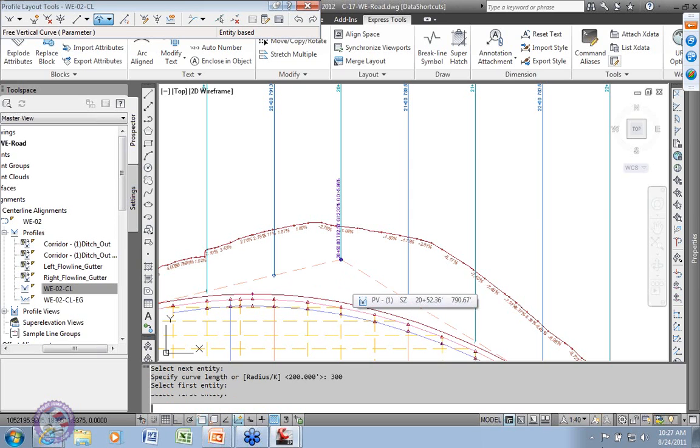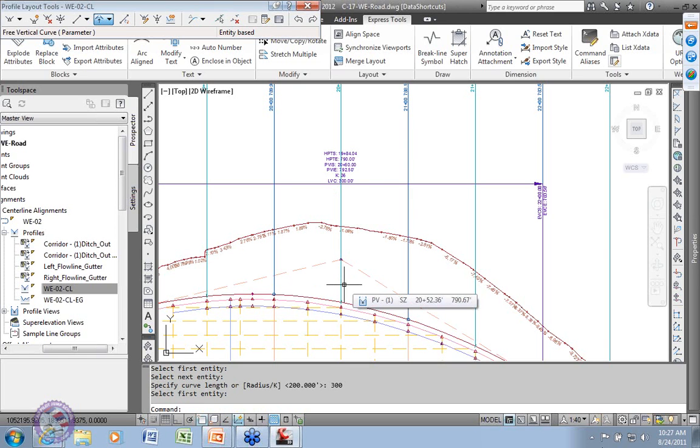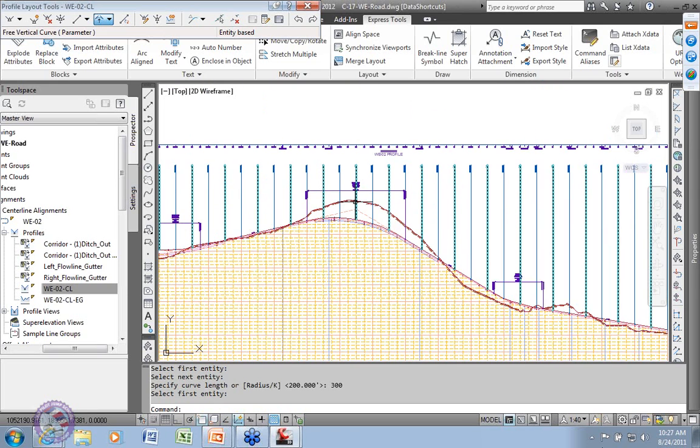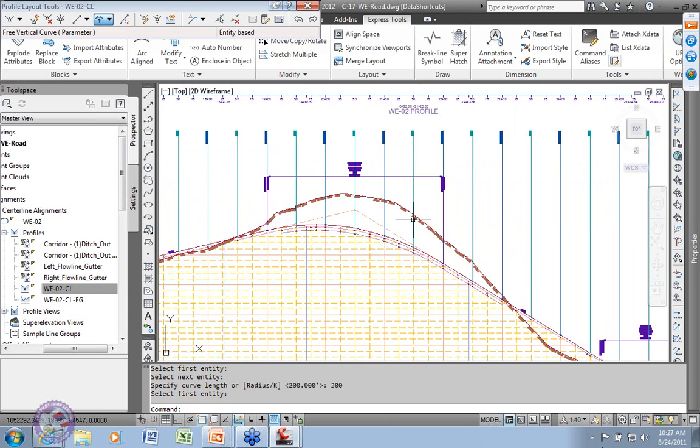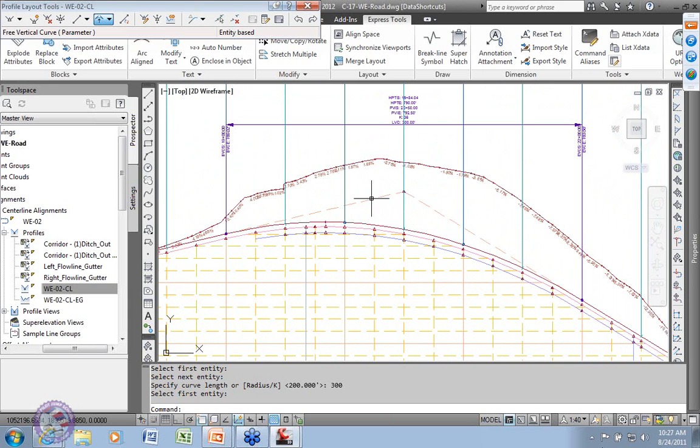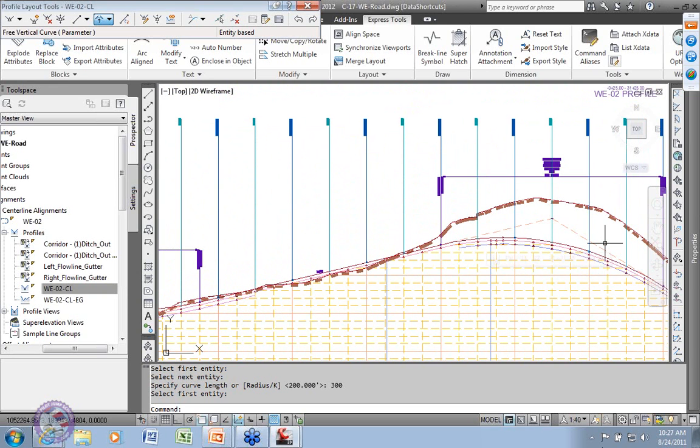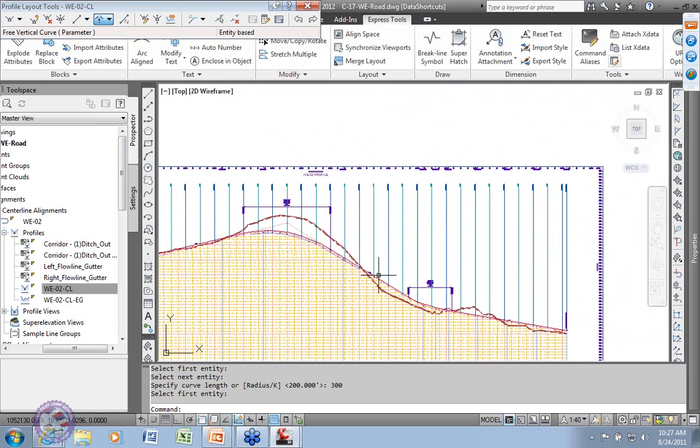Once again, it's Civil 3D vernacular. We have now redefined our curve, and it's now symmetric parabolic. Pretty darn easy. So pretty much you can sketch out a set of tangents, apply the proper vertical curve, get the PVIs in the right location, and massage the entire beast.